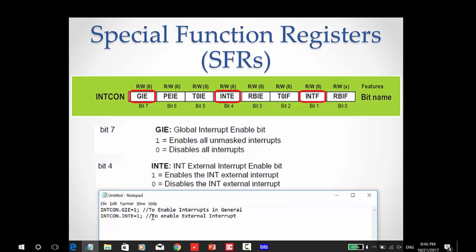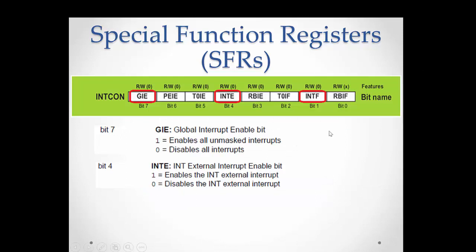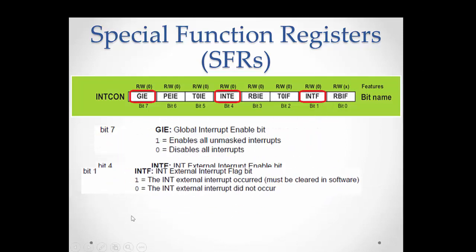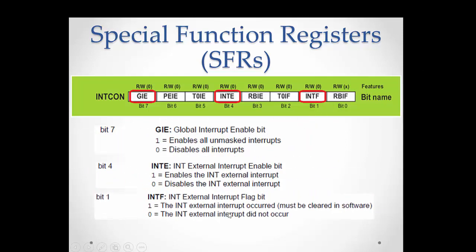Okay, and last but not least, the INTF. This INTF is the interrupt flag, and this is really important. Think of it as a flag. When an external interrupt occurs, this interrupt bit will have a 1. Whenever there is no interrupt, it will have a 0.